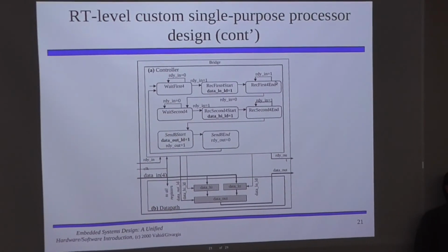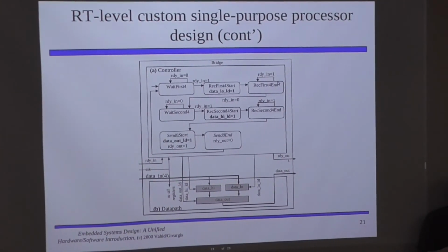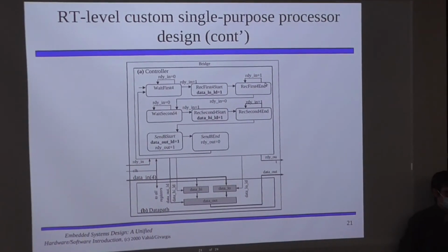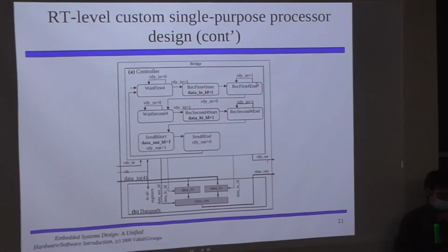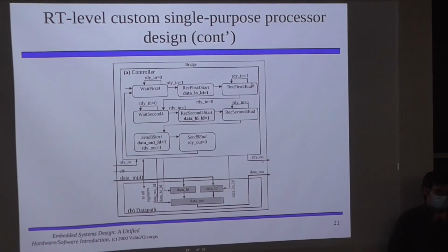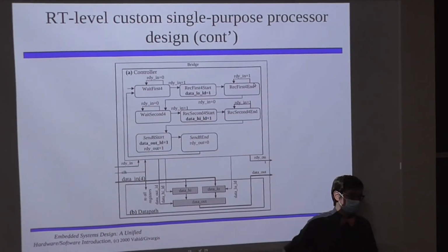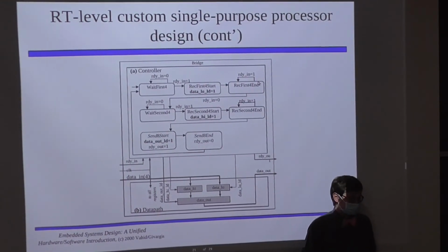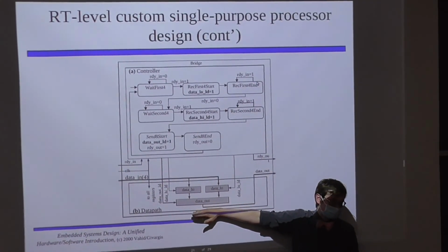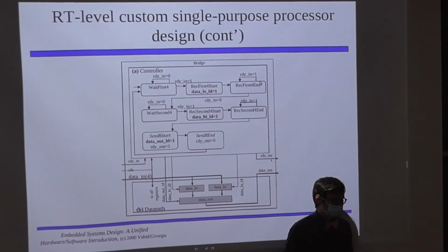So basically the controller is just saying when to load values from an external data line, more or less? That is exactly and precisely. So we're loading the 4 less significant bits and the 4 more significant bits, and then in the seventh state, which would be 6, we're loading it all into 1, and in the last state we send it out, more or less. The way that registers work is that they're always being sent out implicitly. So when we load it, that means in the next clock cycle, anybody can read it. It's not changed again until it goes through all the states again.